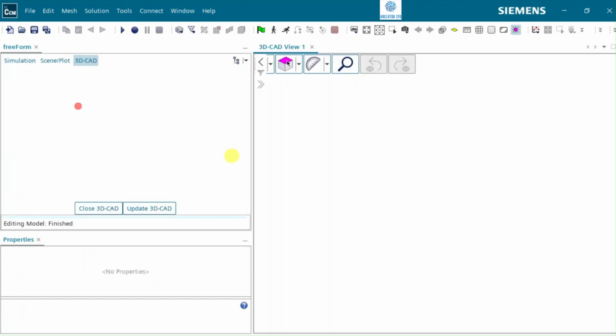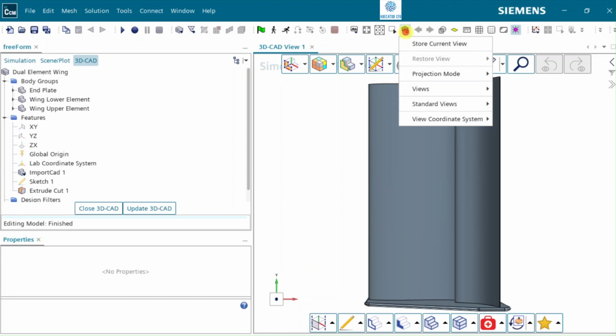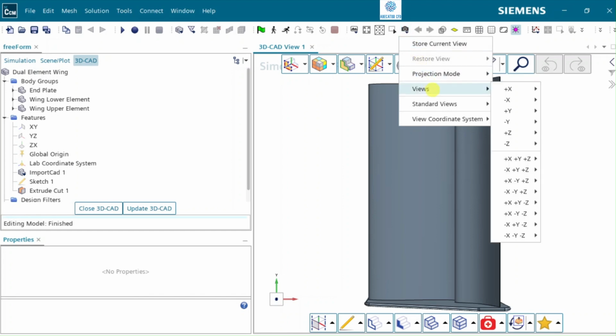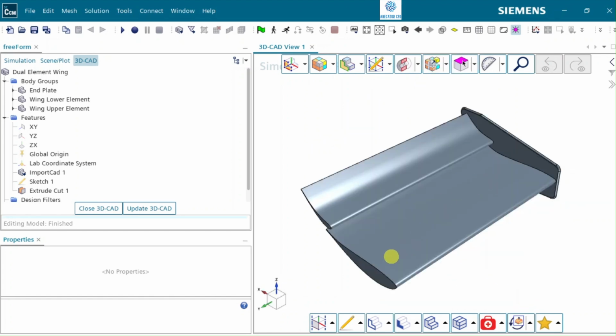At this point, we want to deform the lower wing element. But before the Freeform surface tool can be used, there is one important limitation to keep in mind. It only works on a single surface or patch. That means we first need to prepare the geometry properly. The wing in this example is already cut in half because of symmetry. So the lower element still has a face lying on the symmetry plane, and that face needs to be removed.